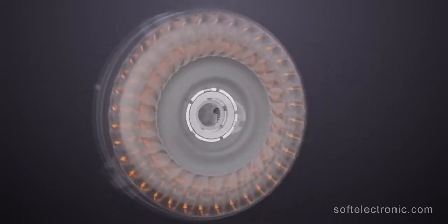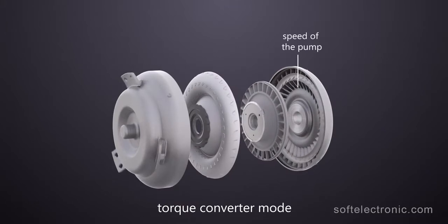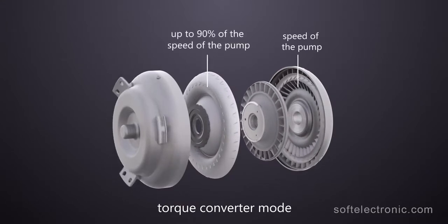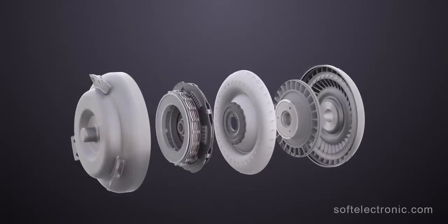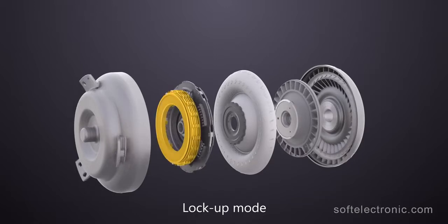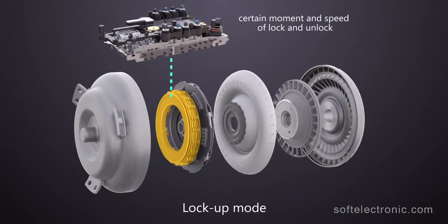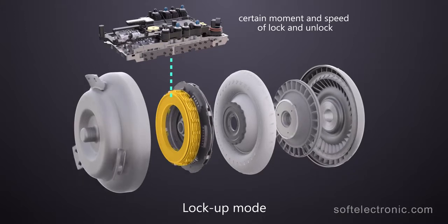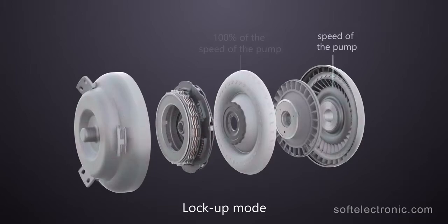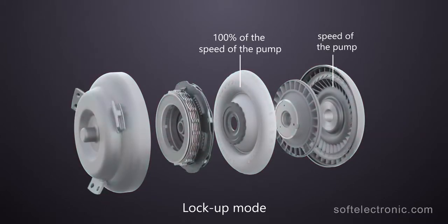The maximum speed that the turbine can reach compared to that of the pump at high RPMs in torque converter mode is up to 90%. Upon reaching a certain speed and acceleration, the lockup mode of the torque converter is activated. The mechatronic controls the moment and smoothness of the lock and unlock, thus establishing a firm connection between the engine and transmission. In this mode, all components in the torque converter rotate at the same speed.